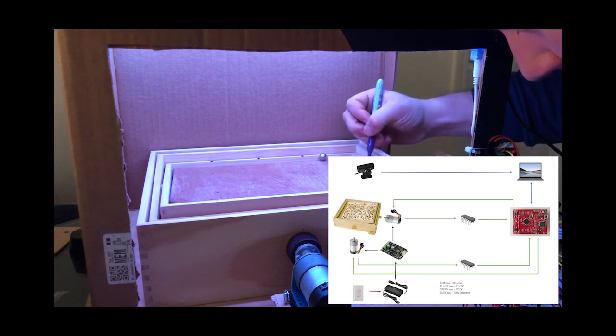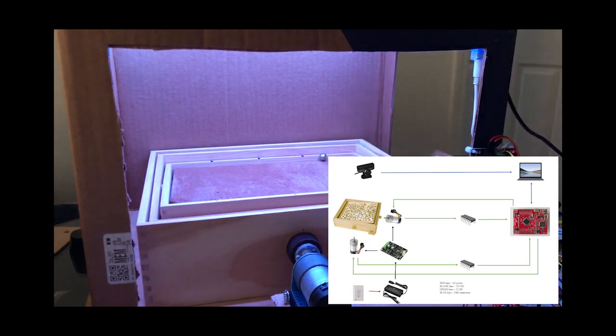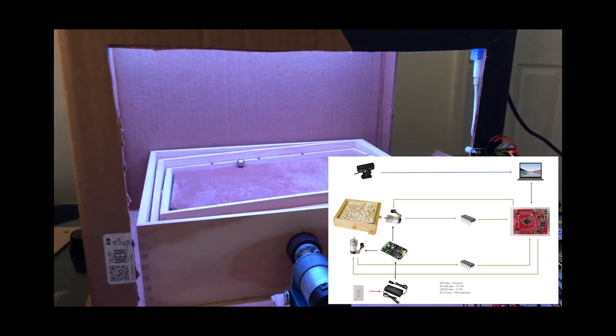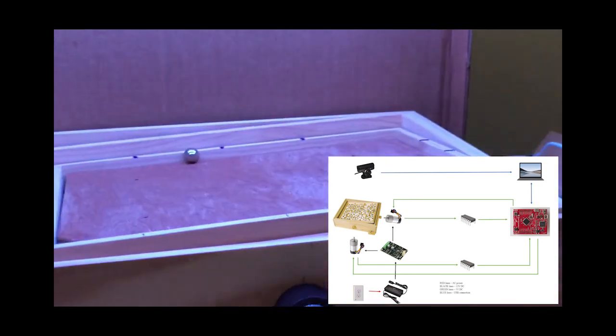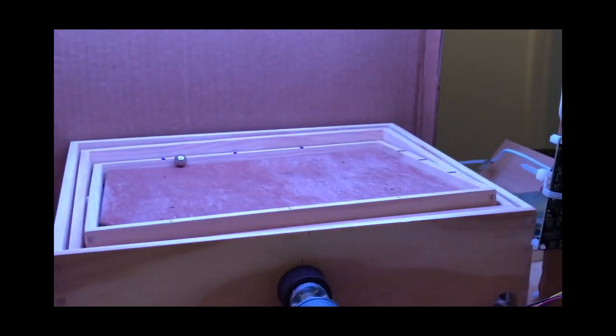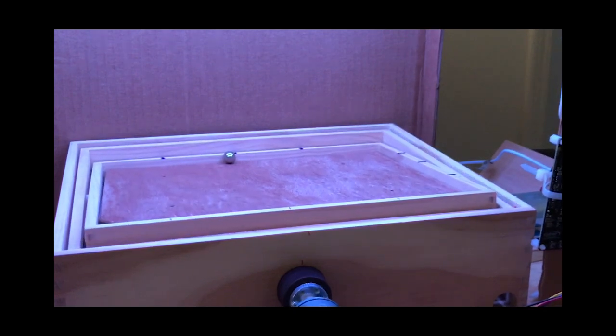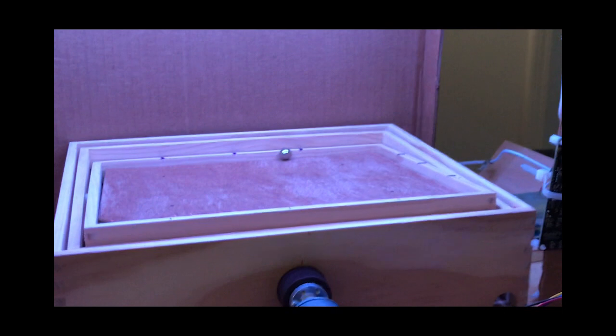The motor controller is given a desired angle we want the motors to turn to and the current angle of the motor, and is used to determine how fast and what direction the motor needs to turn to get to the desired angle. The desired angle is received from our ball controller, and the current angle is received from the counter chips that we used. The ball controller is used to determine how far the board needs to tilt in each direction to move the ball to the correct position.